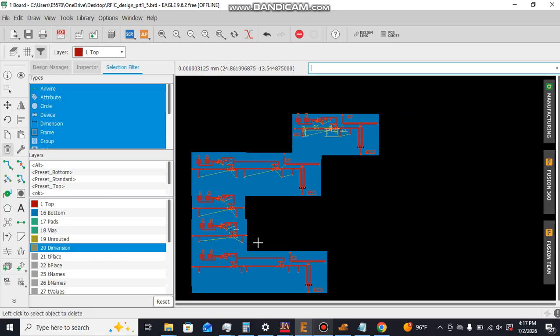I just wanted to test them because I used my software to figure out what the source reflection coefficients would be, so that I could get a way to know what stub matches I need for my matching circuits for the input and the output of the low noise amplifiers here.